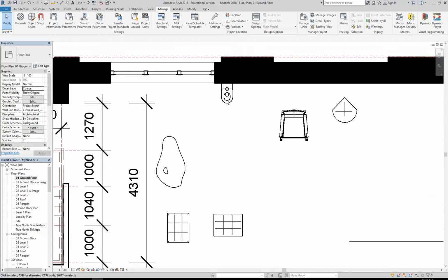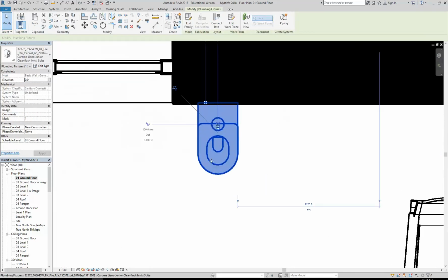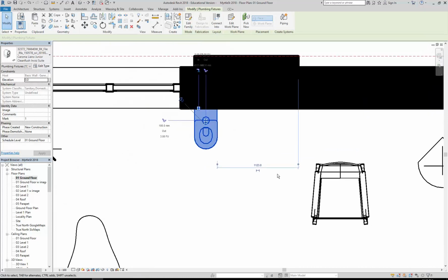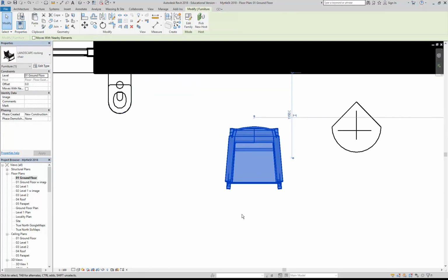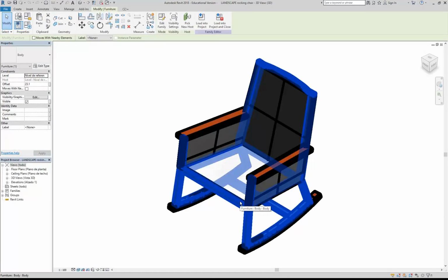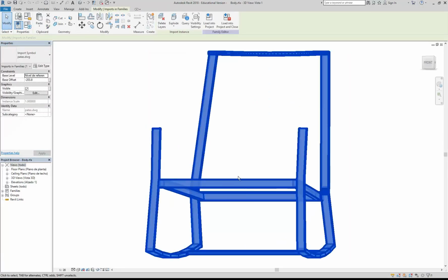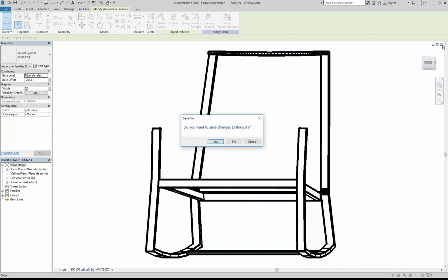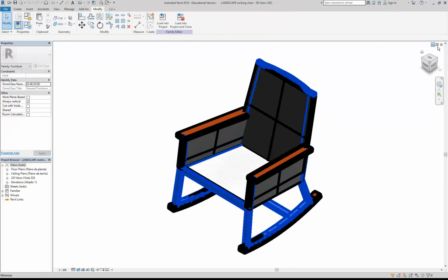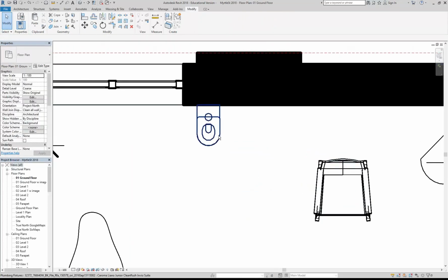And I will just show you one very last thing there. If I select this one here, I know that that one has probably been made a bit differently. So the one that I downloaded first for Modeler, I'd be pretty sure that's been done in AutoCAD. And I'll know if I go Edit Family and then select it. Okay, we've got to go and edit this part. And then I can see, yeah, you can see there, DWG. So at its base, that is actually an AutoCAD model, which is quite difficult to modify and manipulate in Revit. So you'd see that and you go, right, if I want to make changes, well, I'm out of luck, and I'd need to find a different family.